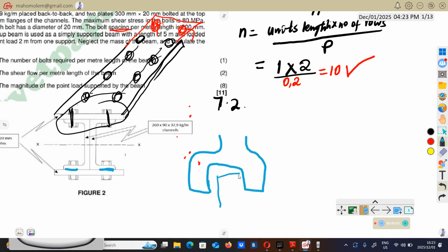Then you put a bolt like here, and your bolt will go like this. Then this bolt will be pulled down here, and this clevis bolt will pull up. So you will have shear here and shear here, then we'll have double shear in that way. In this case, we are going to have a single shear.